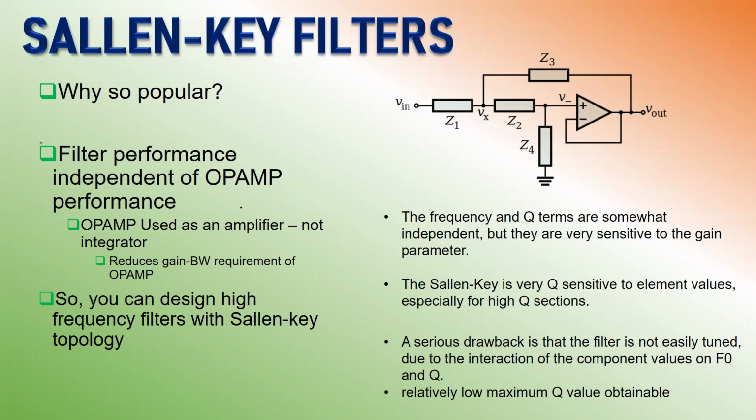So basically, when you design a filter, for example a low pass filter, the transfer function, let's say VO over VIN, can be configured like this. So this is the characteristic of a low pass filter. Here is a slope of, let's say, minus 40 dB per decade, because Sallen Key has a slope of minus 40 dB per decade because there are two poles in the transfer function.